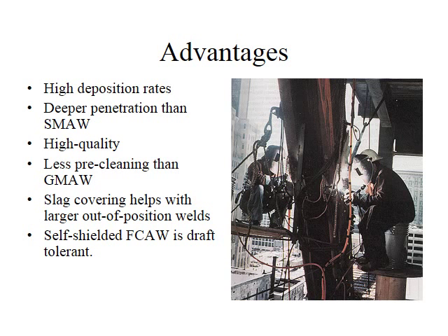The major advantages of flux-cored arc welding are reduced cost and higher deposition rates than shielded metal arc welding. Flux-cored arc welding can also be used in outdoor situations that might not be ideal for gas metal arc welding. It is ideal where bead appearance is important and no machining of the weld is required. Flux-cored arc welding without carbon dioxide shielding can be used for most mild steel construction applications. The resulting welds have higher strength but less ductility than those for which carbon dioxide shielding is used.